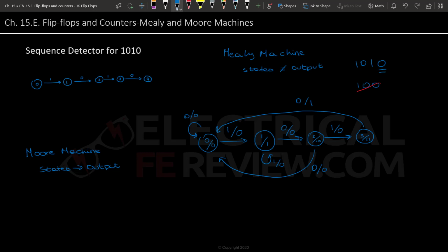And then finally, if we are in state 3 and we receive a 1, what we are going to do is again consider it a new circuit, but display a 0, since the sequence that we would have would be 1, 0, 1, 1, and this is not the sequence that we want. So it is going to go back to our first state, because we're considering a whole new circuit now, but it will give an output of 0.